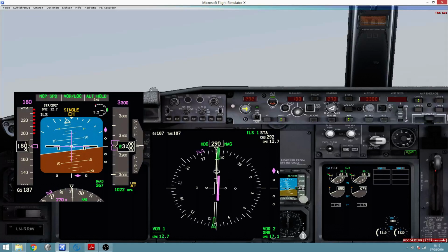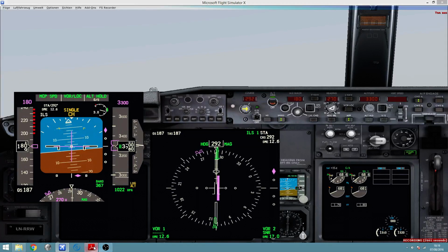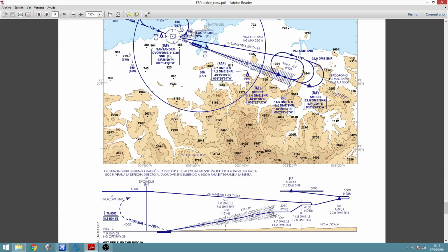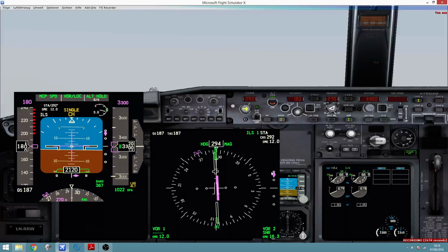And now the glide slope, as we come into the threshold, the glide slope that is currently above our aircraft, we will get to cut it and then continue down with it. You see how the glide slope is coming down here, and as soon as it gets to this middle point, meaning the position of the aircraft, this glide slope will convert from white to green, indicating that we've captured the glide slope.